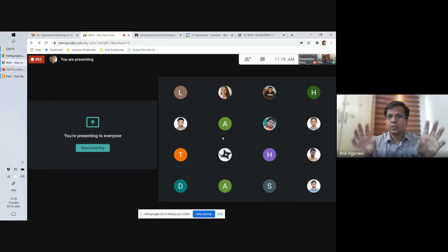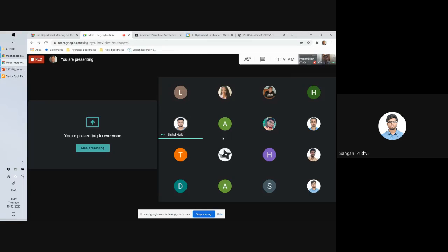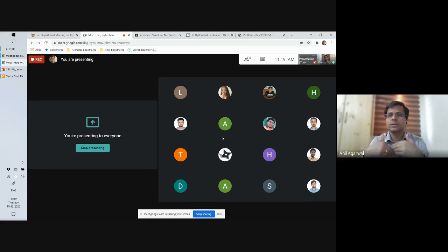A is equal to S D, and if suddenly S becomes nonlinear, what does that mean? It means that for different values of D, my S does not remain constant. So as I change my value of D, if D is equal to 1, any unit you can assume, my S is a certain value, but as I increase my D value to 2, my S changes its value. Then can I say that A1 plus A2 is equal to S times D1 plus D2? No, because my S was changing its value along the way. Agreed? Yes, sir. Right? So that's when the problem becomes nonlinear.